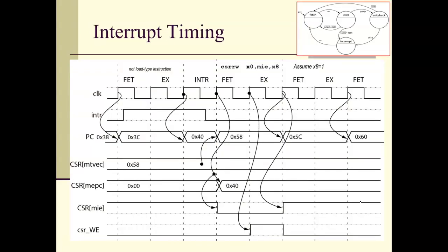So here's our diagram, and what this one is showing is how fast I can get those interrupts re-enabled. Okay, so here's an instruction. Here you've got your interrupt coming in here, turns off here, great. You go into the interrupt cycle, etc., etc. This is mostly the same picture as before, but I'm going to say this is the address of my interrupt service routine. The first instruction re-enables the interrupts. Not something I'd really want to do, but for this problem, we're just going to talk about it.